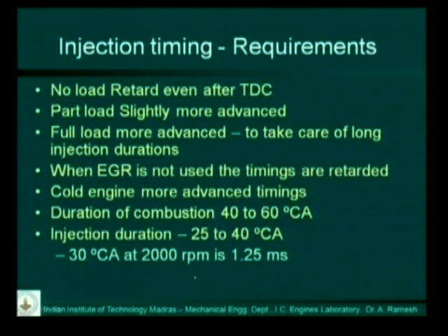And the duration of injection could be something like 1.25 milliseconds. Total duration may be only that. It's a very, very short duration. And in that short duration, you have 2 pulses, 3 pulses or 4 pulses. So it becomes complicated.